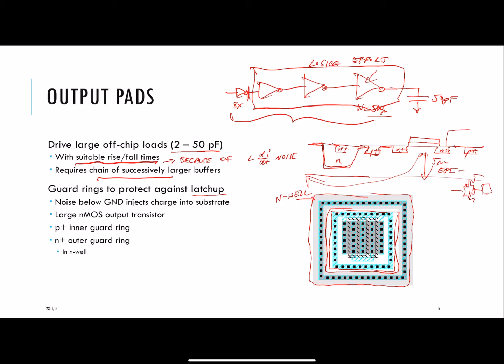If some bad voltages happen, which normally don't happen inside the chip, let's say a low going glitch below the ground level, which could happen if you're looking at the outside of the chip, that structure is going to end up looking like two back-to-back bipolar transistors. Again, it's called latch up. They'll give each other positive feedback, and your chip will go into a condition called latch up, and it might be destructive to the chip if you can pull enough current, or it might just freeze your chip.